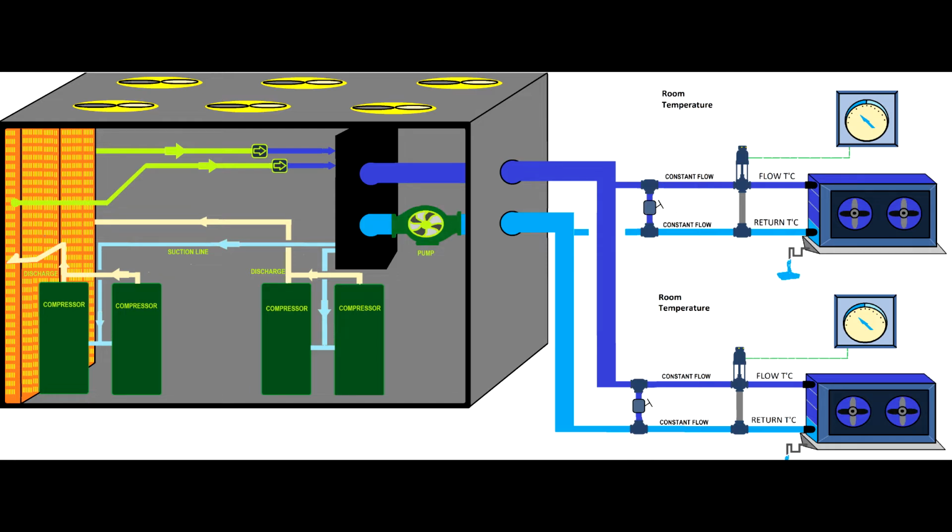You really have to measure the water flow temperature, not the return, the water flow temperature before the three-way valve. So it is very important, because at that point we're looking for a constant flow and a constant temperature. That will allow the three-way valve to control the heat exchanger capacity if you use a proportional control. And I will talk about this later on. But let's now keep it simple.